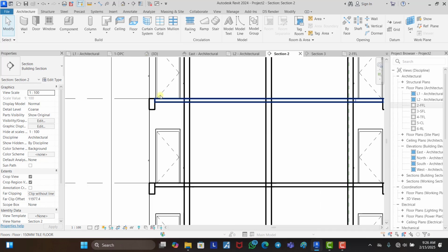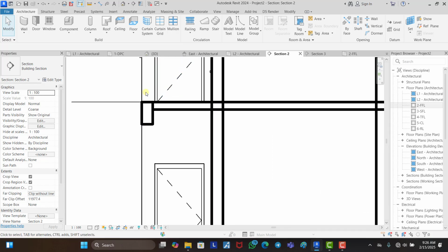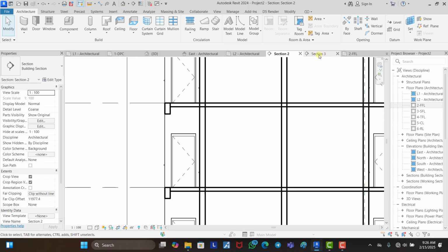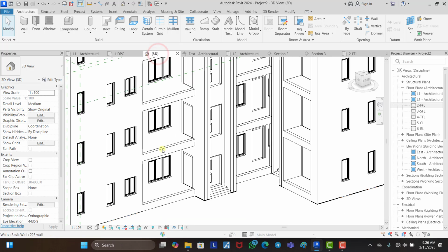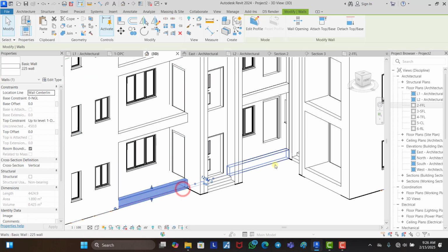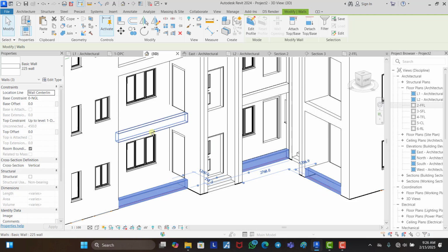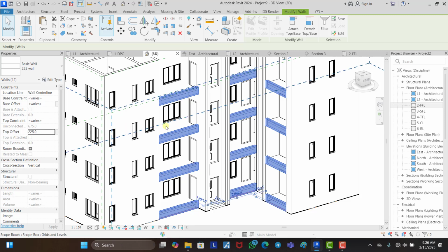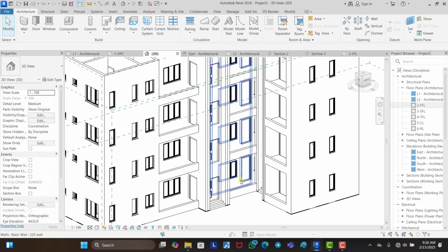Okay, then we can also decide to have an upstand, a small upstand beam at this point. So as we have this drop down, we can also have an upstand beam of 225 at this point if we want. I think that would look nice, so let's just do that. So you can have this 1, 2, 3, 4, 5, 6, 7, 8, 9, 10, 11, 12. Perfect. So let's set top offset 225. Perfect. Good. So now we have that upstand.